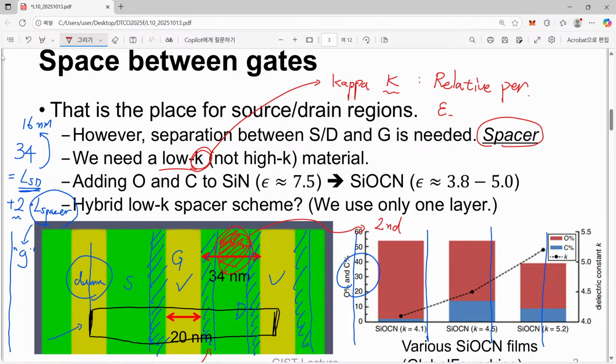For example, when I say this epsilon silicon, then it really means the permittivity of silicon, and this corresponds, for example, to 11.7 times epsilon 0. So this number, 11.7, the relative permittivity, is sometimes just written as epsilon or sometimes written as kappa silicon.